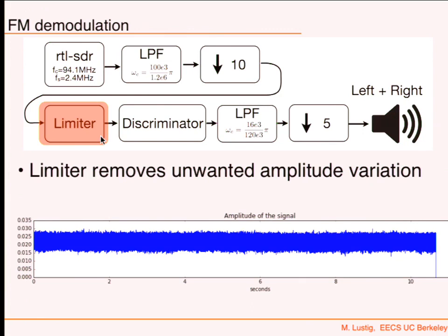Now you've got a signal normalized in magnitude to 1, but it only has phase variation. That's it. Divide by the absolute value. Now, if you divide by the absolute value, maybe there was a chance that something went to 0, and then you've got yourself a numerical problem. So you're going to divide by the absolute value plus some epsilon, just to make sure you don't have this effect. Okay? So this is really the amplitude of the signal, and you see because of noise and other things, it has deviations.